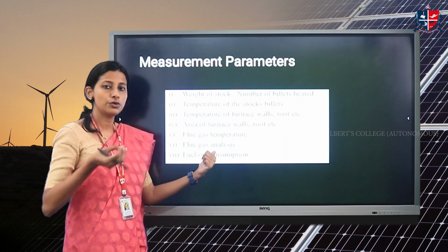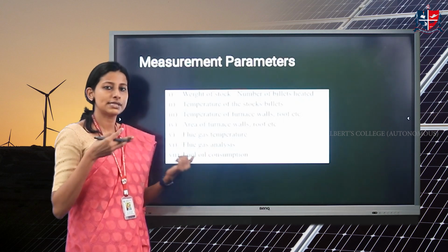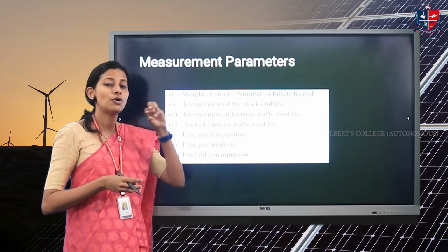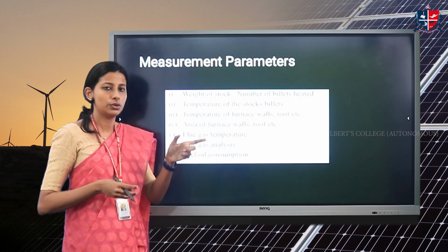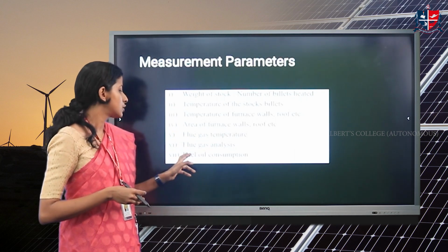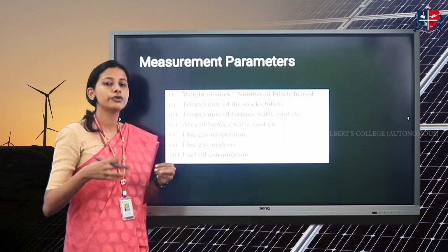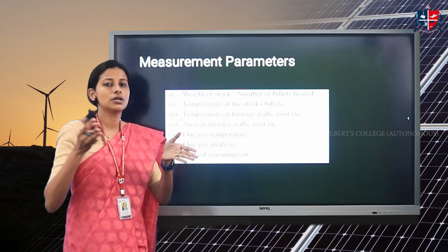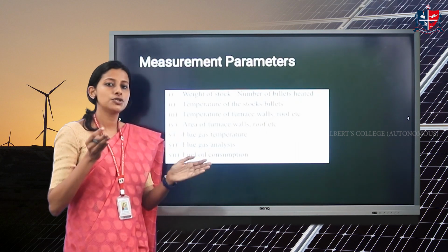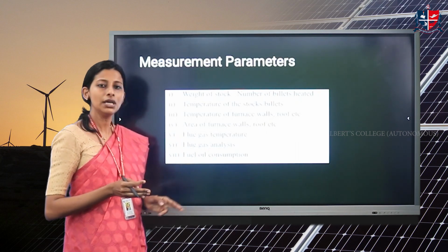You have to analyze the different components. There could be oxides of sulfur, oxides of nitrogen, etc. You need to closely monitor the type of components coming out, and whether they are causing environmental degradation. Also, the fuel oil consumption: how much fuel oil is being consumed for heating, say, 1 ton of steel? How much fuel is required? That also has to be monitored.